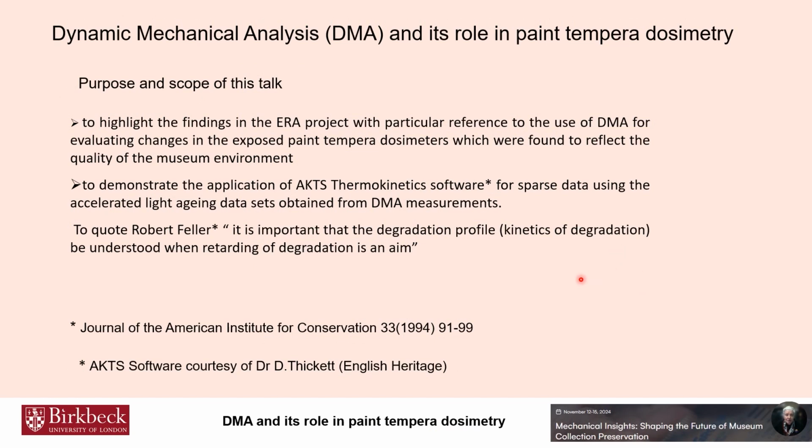So the purpose and scope of this talk is to highlight the findings in the ERA project with particular reference to the use of DMA for evaluating changes in the exposed paint tempera dosimeters, which were found to reflect the quality of the museum environment, and then to demonstrate the application of the recent ACTS thermokinetic software for sparse data using the accelerated light aging data sets obtained from DMA measurements.